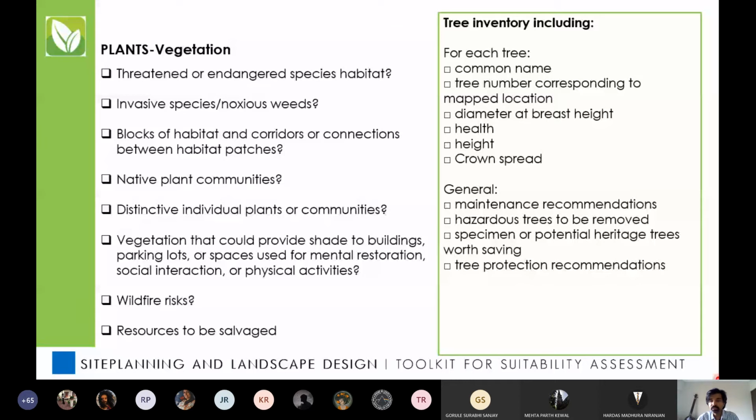So when New Delhi was designed in the last century, when the trees were planted on the sides of Lutyens Delhi, they would never pour water at the base of the tree sapling. What they would do is, around 10 feet away from the tree, they would have a perforated terracotta pipe which is inserted into the earth, and then filled with gravel. The gardeners would pour water into those pipes. So these are perforated pipes in the soil.